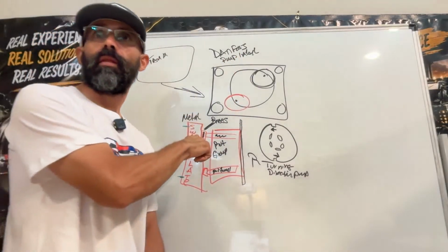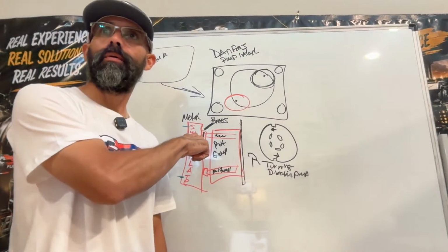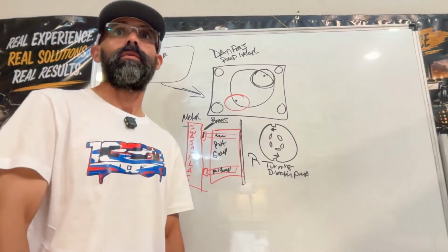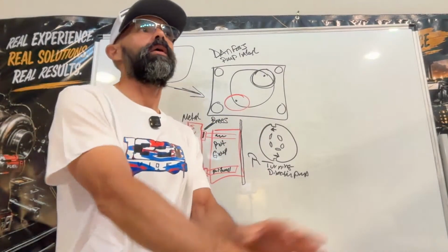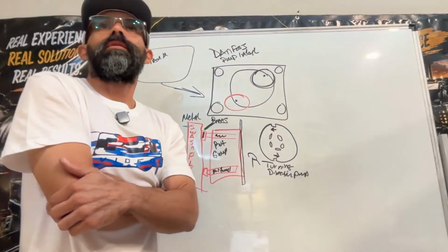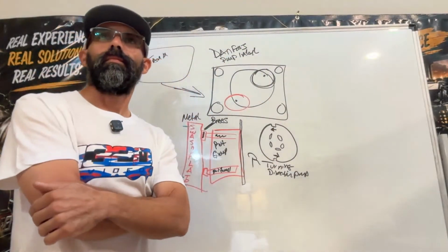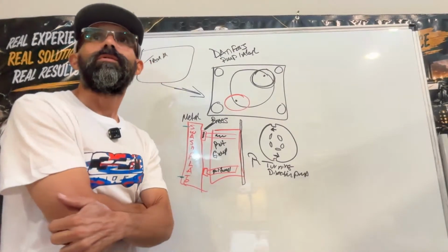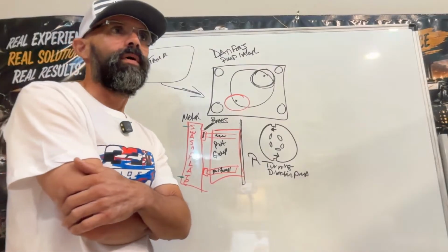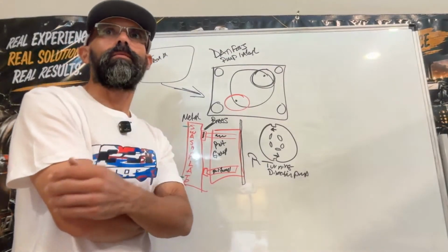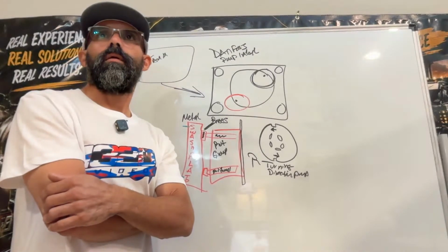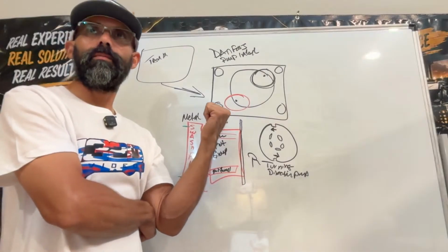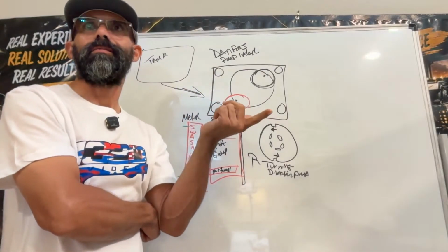But remember, if you buy a new pump and you put it back on a contaminated system and you destroy the pump, don't expect any warranty. You know what? There's no warranty on this. It's on you. And now you're going to tell the owner of the equipment, hey, you know what, man, there's no warranty. They're not going to pay for it. Of course not. It wasn't their fault. It was your fault because you didn't clean the system. So whether you buy a new pump or rebuild the pump you're working on, clean the whole system.